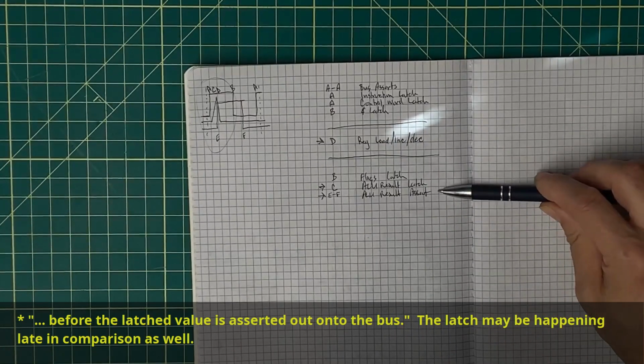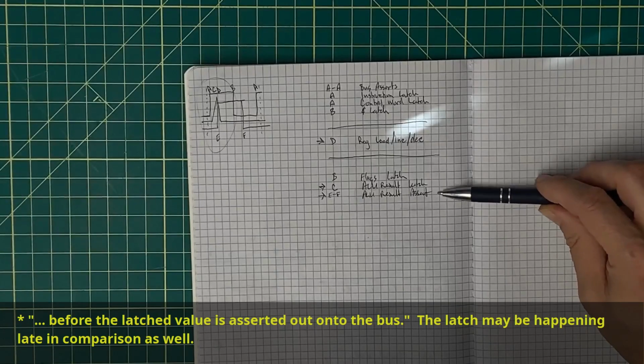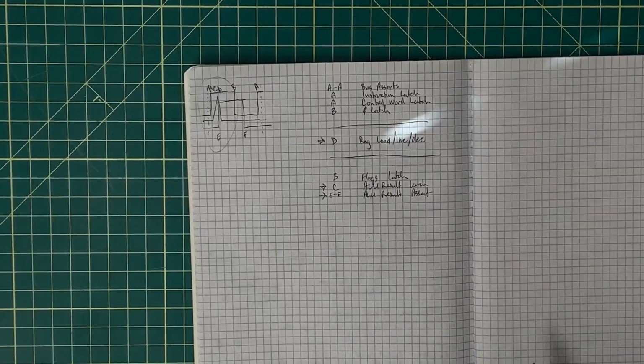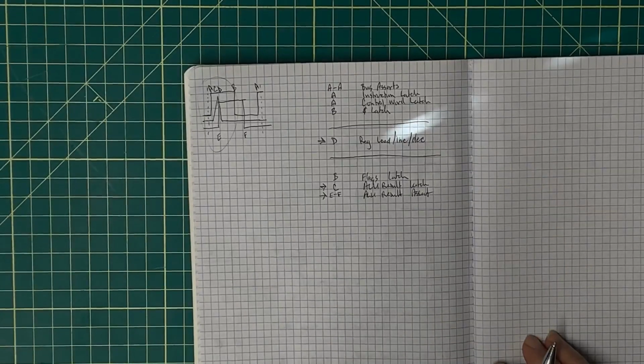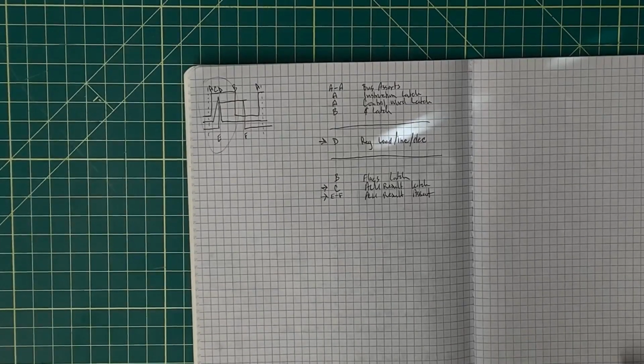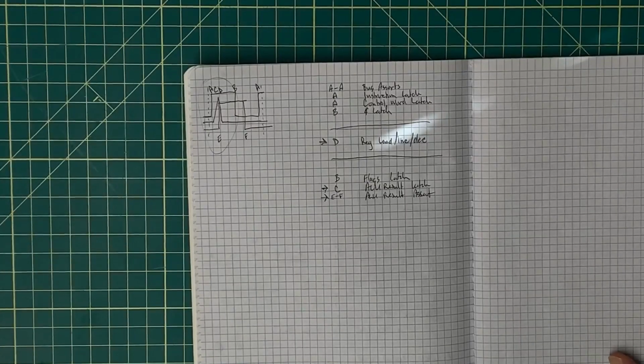I want to make sure that I'm actually latching at the correct time, that I am doing the result assert, and make sure that all of that is happening sequentially properly. So I'll grab the build again, pull it back out, zoom back out, get myself set up, and grab the oscilloscope, and let's see if we can measure this sequence and make sure that things are happening in the right order.